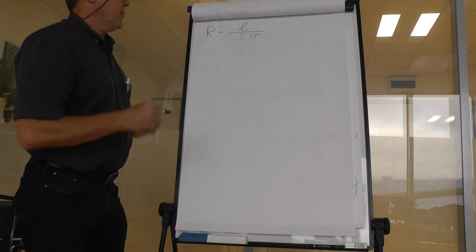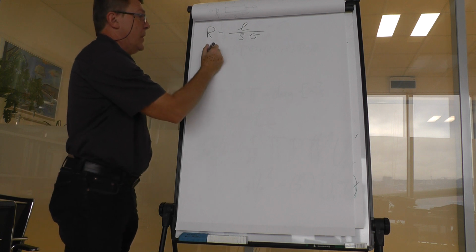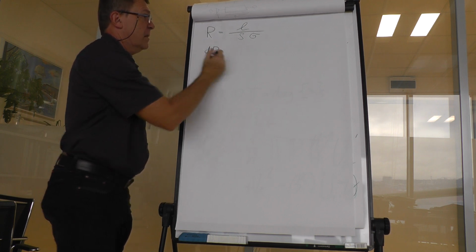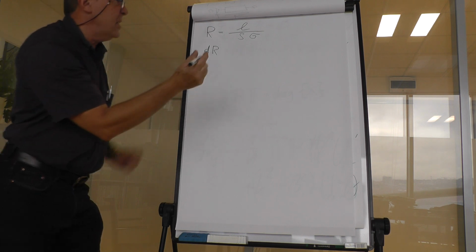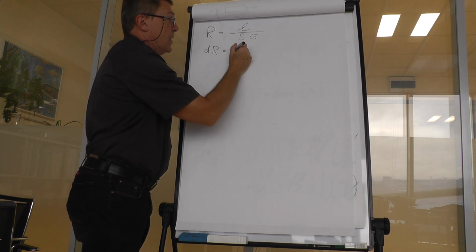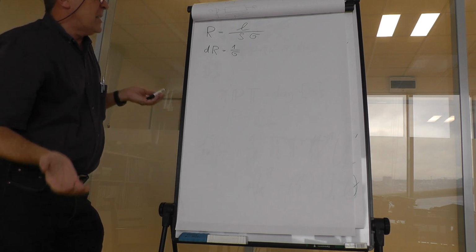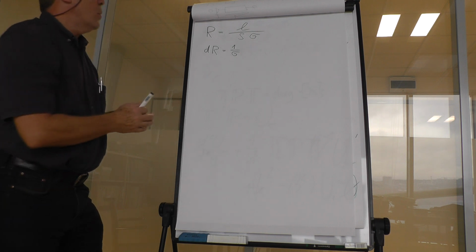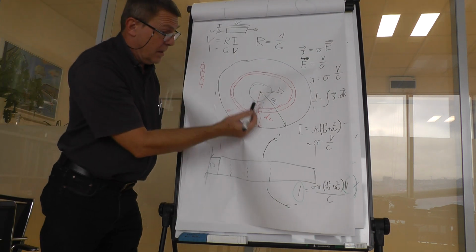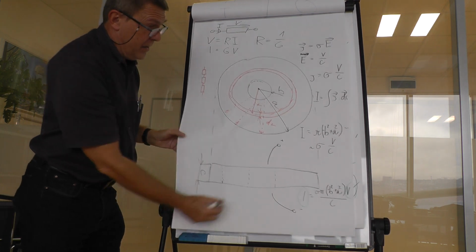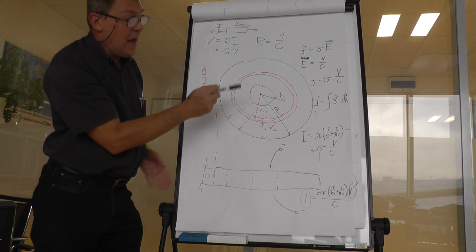We can follow this equation so that we would have dR, the value of the differential piece of that resistor. It would of course be inversely proportional to the specific conductivity of the material. And now there is the length and the surface. The length of the current path through this resistor is dr. It just flows radially out. What is the surface?